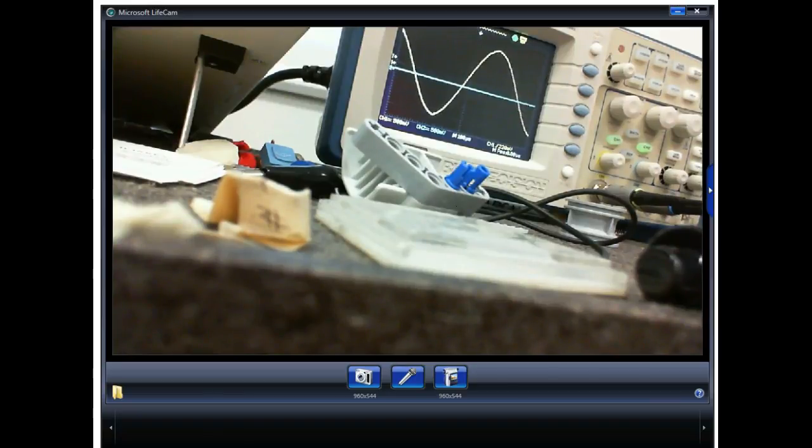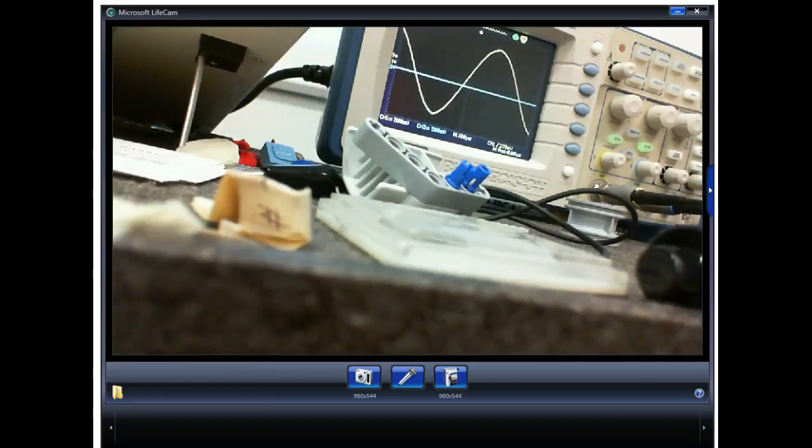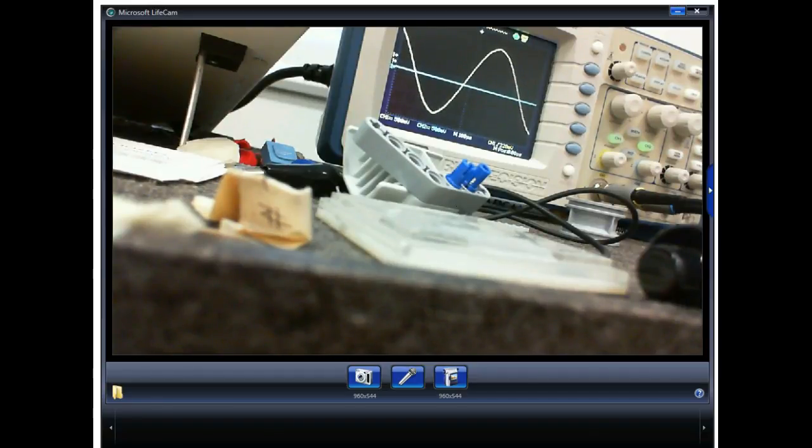So normally when we troubleshoot, especially amplifiers, we start troubleshooting with an oscilloscope if we got one. Right? Start at the what? Output and work back toward the what? Input until we find the signal. And whatever we went through last, kind of like motor controls, has to be the problem. Then we get our meter out and we check the bias. If the bias is right, we consider the amplifier okay. But sometimes we have subtle little hints that we've got a problem. And what's the subtle little hint here? We don't have that 6/10 of a volt or 7/10 of a volt drop between the base and the emitter.